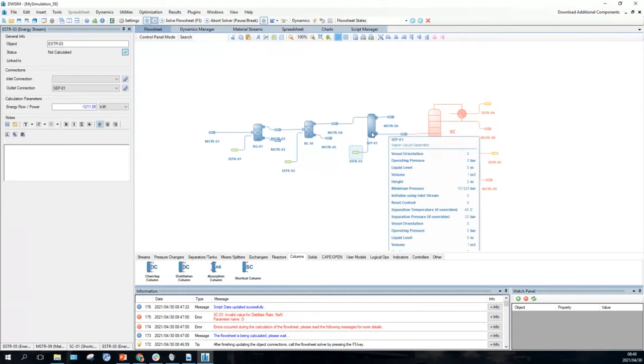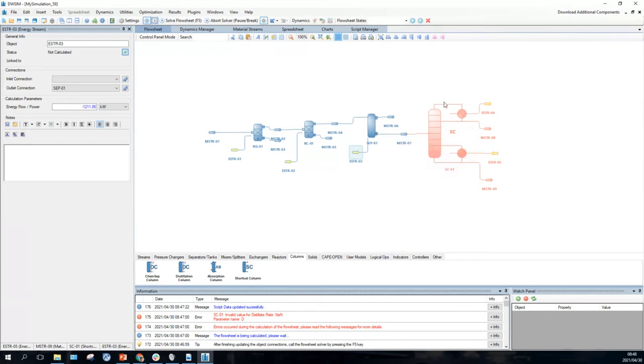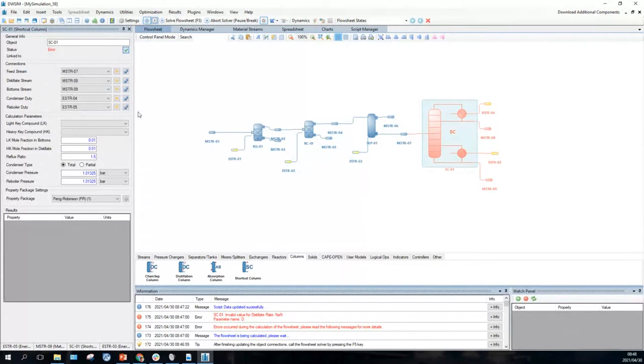I don't think high pressure really helps, but I'm using a high pressure here for illustrative purposes to see the importance of using a partial condenser here. So this is water and methanol. Now we go back to, oops, click that. We go back to what is the light key component. That will be methanol. What is the heavy key component? That will be water.